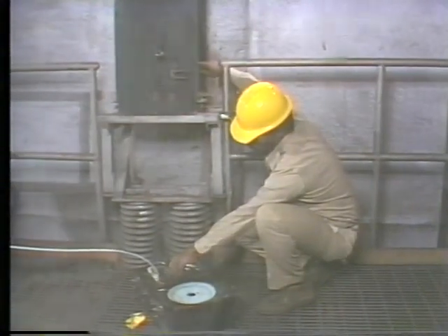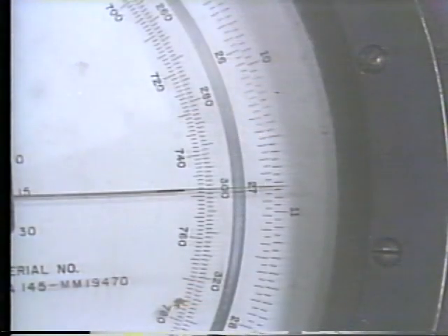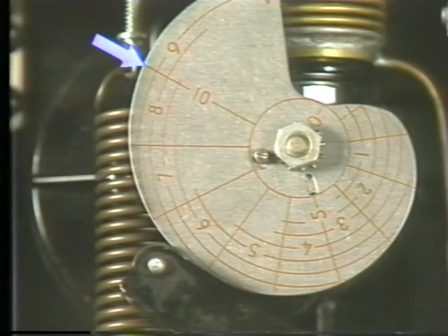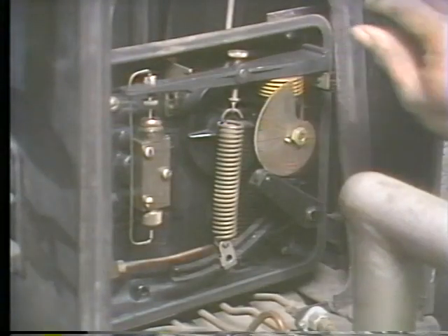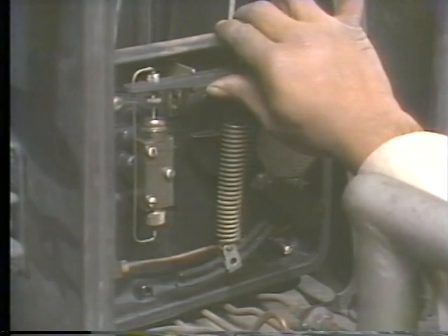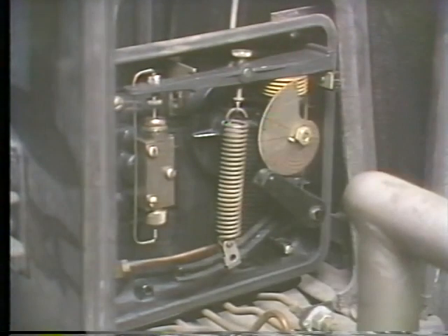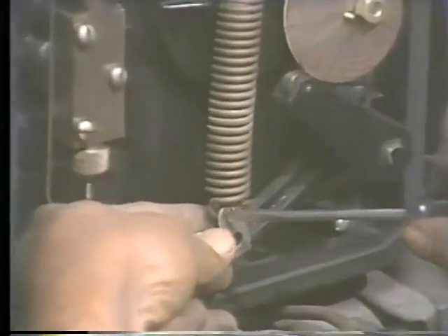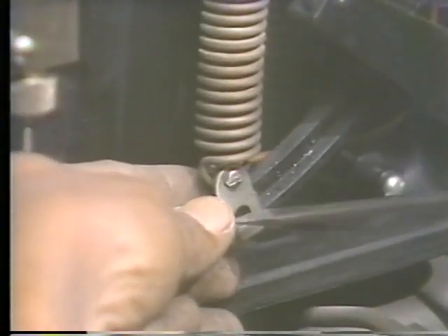In your plant, or for other applications, the maximum loading pressure could be 15 psi or any number of other maximum pressures, depending on the instrument and the manufacturer's specifications. When the loading pressure is at 27 psi, the cam should indicate its maximum travel, or in this case, 10. If it doesn't, lift up on the balance beam. If the cam moves, then the piston and louvers aren't at their fully open positions, and the positioner needs to be adjusted so that the cam indicates 10.